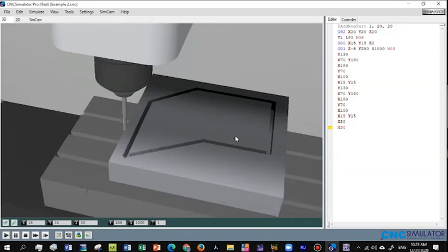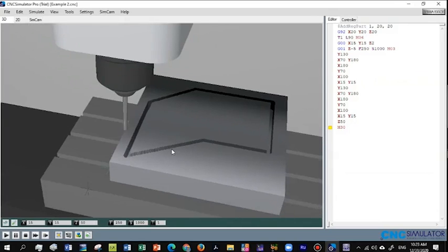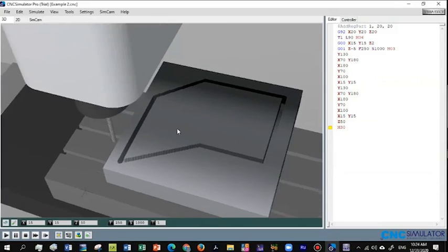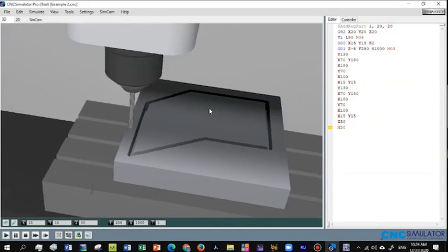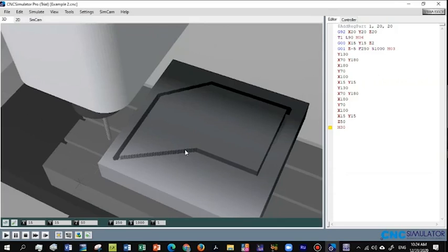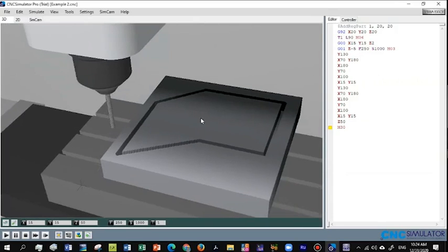I mean, it's not compulsory to use the exact dimension, because the workpiece can be rectangular, so you need to define a workpiece that is a little bit bigger, or it can be much bigger. But at least don't go past the out limits of the allowable machine workpiece. Sometimes if you enter a dimension which is too big, it will show you an alarm telling you that this dimension is out of the limit in x-axis, y-axis, z-axis, and so on. So in this case, you need to reconsider the dimensions that you enter for your drawings.